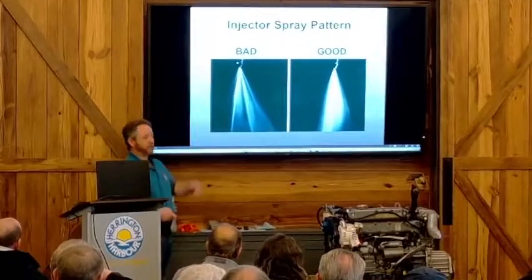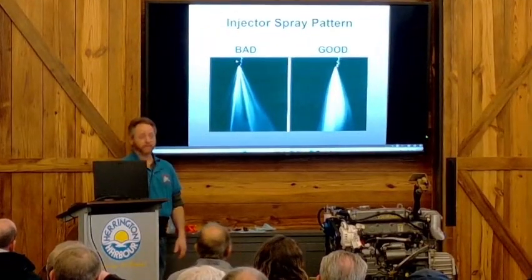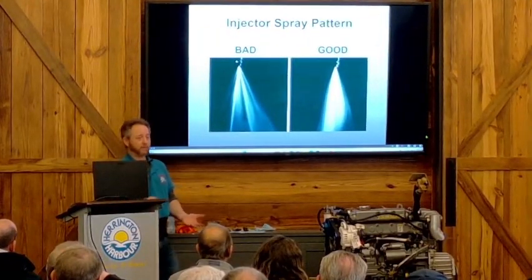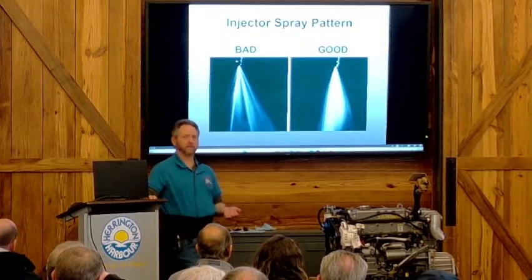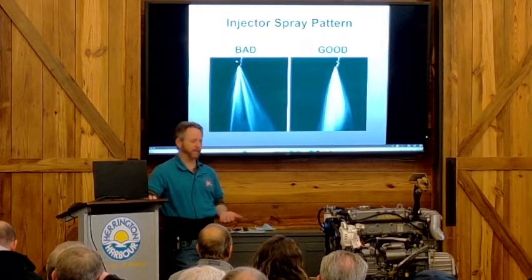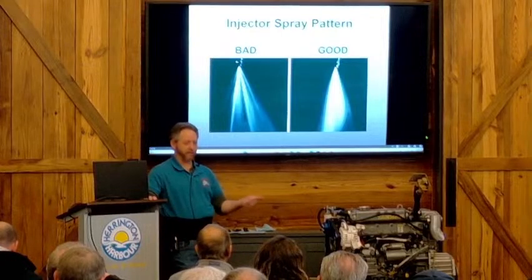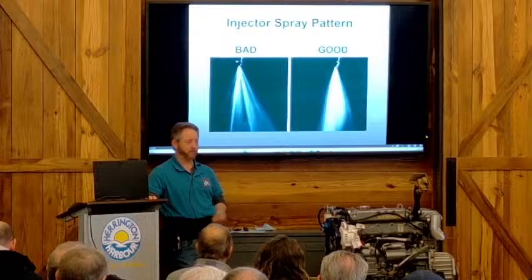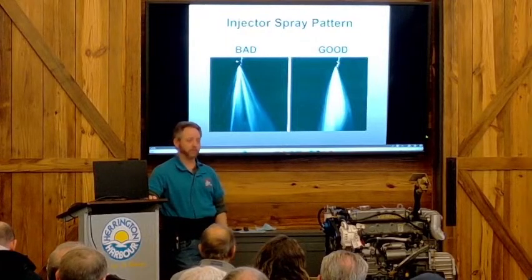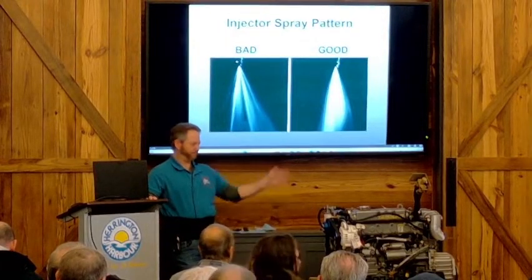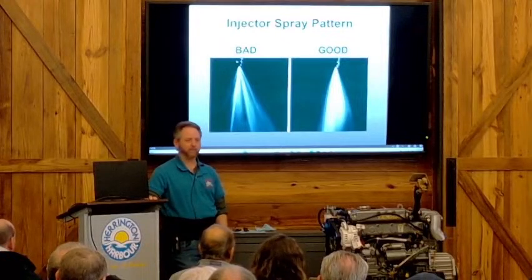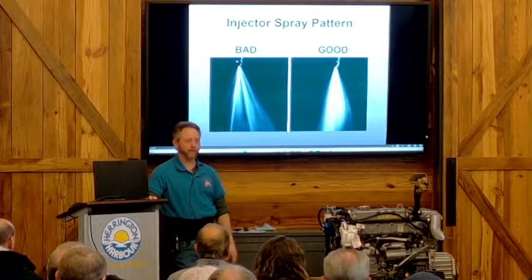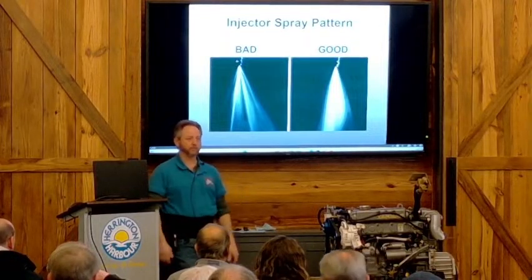We rebuild injectors ourselves. There are some injectors you can't rebuild. A lot of the Caterpillar 3208 injectors we can't do. Some of the 6-cylinder Yanmars we can't do because they have what are called 2-stage injectors, and they have to be put on a special machine. But I would say probably 90% of what we work on, we can definitely rebuild ourselves. And electronic injectors we can't do because they have the little electric solenoids on them.